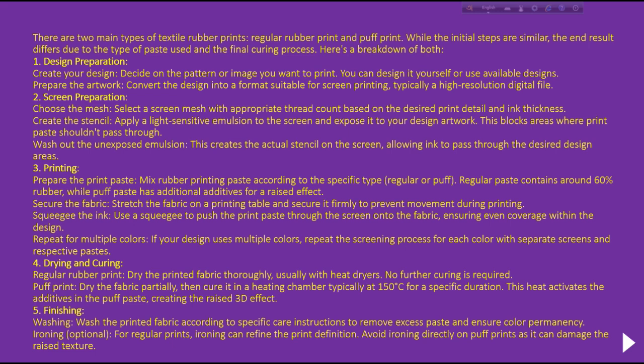Design preparation. First we create design as per our customer requirement. Then after that we prepare screen. Choose the mesh, select a screen mesh with appropriate thread count based on the desired print detail and ink thickness.